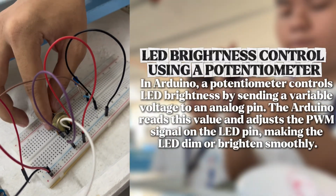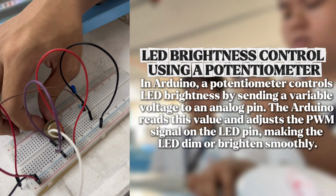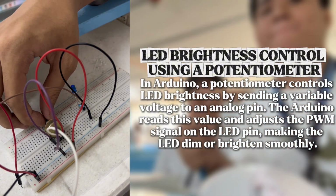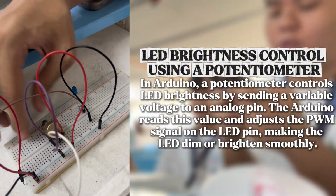In Arduino, a potentiometer controls LED brightness by sending a variable voltage to an analog pin. The Arduino reads this value and adjusts the PWM signal on the LED pin, making the LED dim or brighten smoothly.